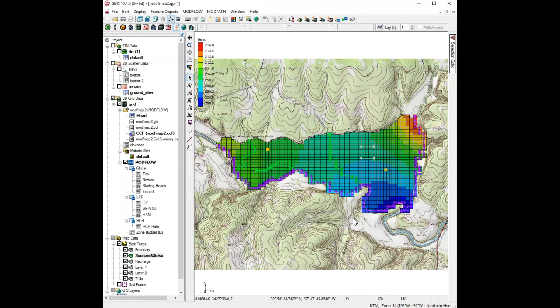If you calculate travel time using Darcy's law directly, you get what's called Darcy velocity, which isn't really the true velocity at which things travel in the groundwater. So you divide the Darcy velocity by the porosity, or effective porosity, of the soil. In order to get accurate travel times, we have to enter a porosity for each of the MODFLOW cells.